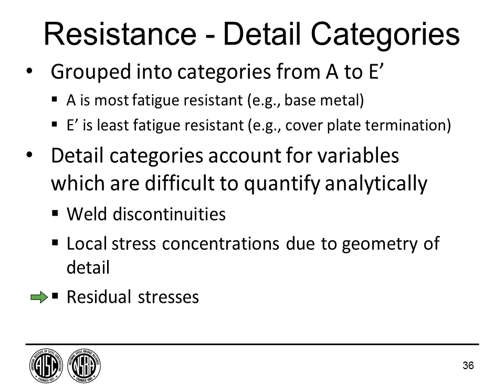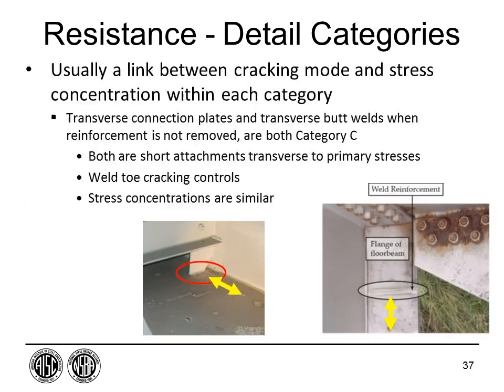And another very important one are residual stresses. In this case for us, generally it's when a weld cools, and we have very high stresses locked into the structure. There's nothing wrong with those, but they have a big influence on fatigue life. These three are very difficult to quantify, if not impossible to quantify numerically. Fortunately, the detail category, since it's based on large-scale test data or full-scale test data, incorporates all these explicitly. So if I do enough tests, I have all this included in my fatigue curve, and that's what we have today.